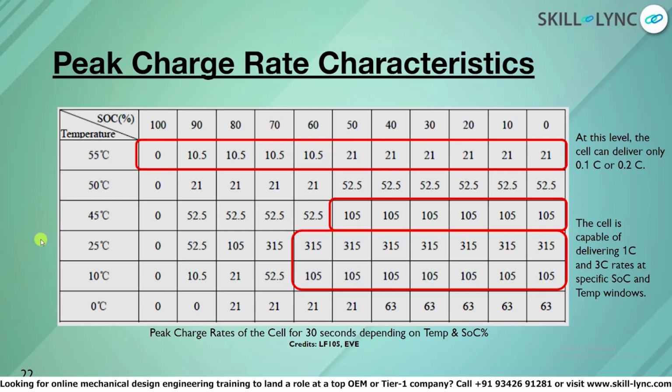That is the disadvantage the lithium-ion cell chemistry has in charging, because most lithium-ion cells are electrolyte filled, and when those electrolytes freeze, the ion movements become quite difficult. So that is how you say below 0 degrees lithium-ion cells should not be charged. So that is how it is.